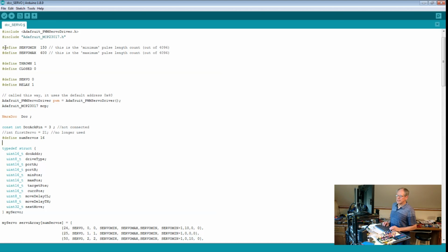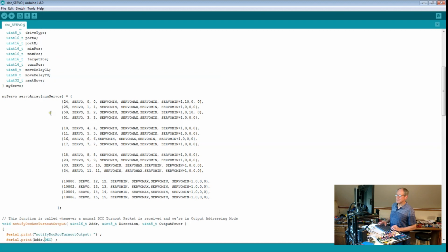Okay, we already did the definition of the data type. Now we are going to add 8 more ports. Since we have 16 relays, we are going to add 8 relay drives, 8 relay addresses, so we make this 24. And that means we have to add 2 more groups to our definition. So let's first just do a prototype and then do some copy and paste.